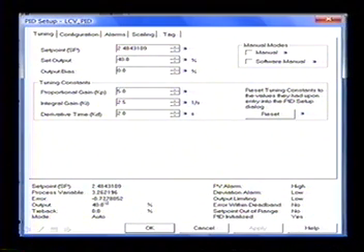So that means that this is too great. Maybe deadband is set at 0. You know, if it's set at 0, well then you're gonna get this. It's not gonna say it's okay. You can actually use this information and send it back to the DCS and say, hey, you know, your deadband, you're not within your error. You've got a problem you can't control. Set point out of range. You can actually set a range for this, and you can say PID initialized, yes.